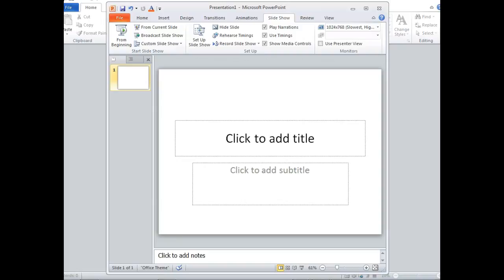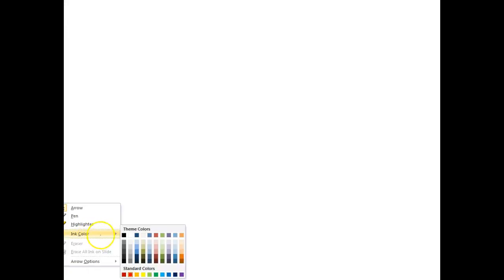Common base is real hard to see because on common base what we do is we input on the emitter and output on the collector. So it looks real strange. And you don't run into that much, and we don't teach them in this class anymore. I don't know if you're going to run into them or not, but you will in some communication circuits.